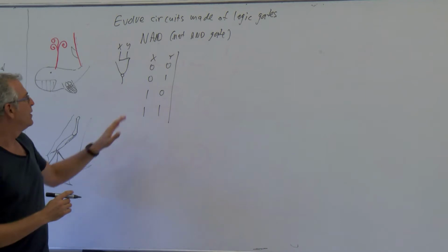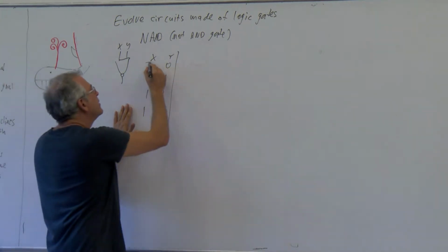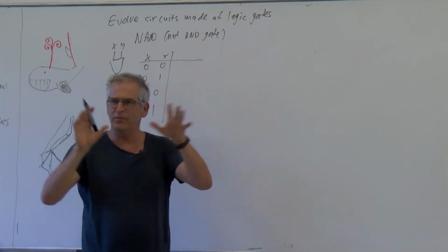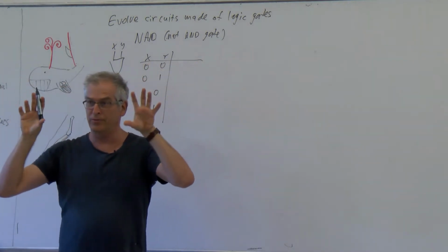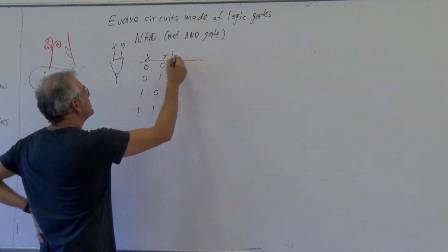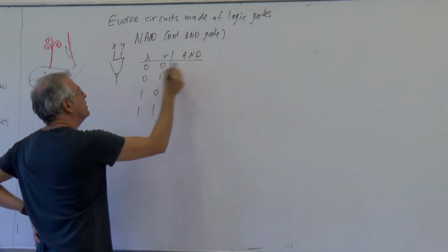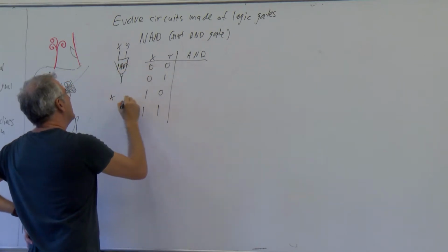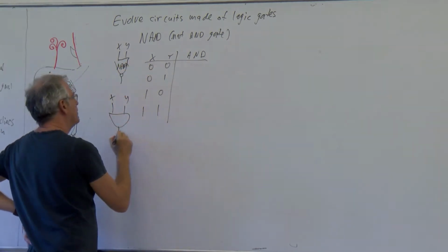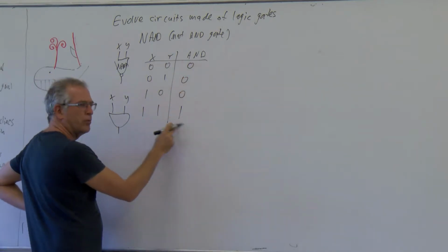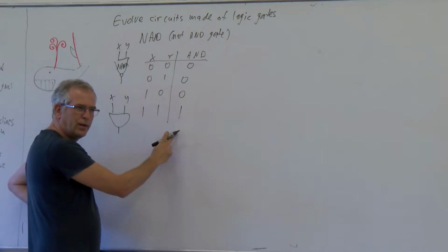Okay. And with NAND gates, you can build the entire custom. So the comment is that engineers use NAND gates because you can build OR gates, AND gates, XOR gates with NAND gates. They're universal. NAND gates are enough to build any logic function. Correct. So let's just start with AND, X and Y. This is NAND. X and Y, you remember, is 0, 0, 0, 1, right? Only when both are 1, you get a 1.